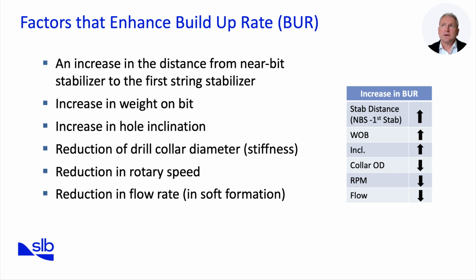Weight on bit also plays a direct role. As weight on bit increases, the tilt force increases, encouraging the bit to climb upward. Hole inclination itself is another contributor, as a steeper wellbore amplifies the mechanical forces acting on the bit. Reducing drill collar diameter decreases stiffness, making the assembly more flexible and responsive to side forces, which again increases BUR. On the operational side, reducing rotary speed or flow rate, particularly in soft formations, also enhances the build tendency.